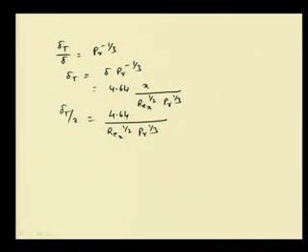That is the factor making the difference between the two thicknesses. As we have seen, with different kinds of velocity profiles we get different delta t by x, but the point is that the temperature profile and velocity profile in the boundary layer have been taken to be of similar form.